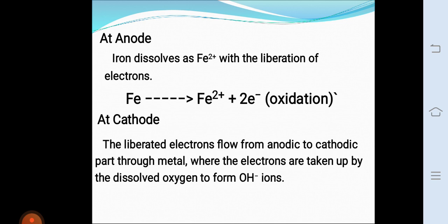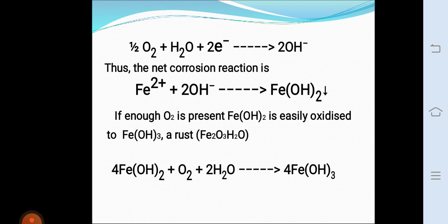That is also a layer of oxide film on the metal. So, the difference between chemical and electrochemical corrosion: chemical corrosion occurs only in dry condition, but electrochemical corrosion occurs in the presence of moisture or any electrolyte. Chemical corrosion is due to the direct chemical attack of the metal by the environment. Electrochemical corrosion is due to the setup of a large number of cathodic and anodic areas.